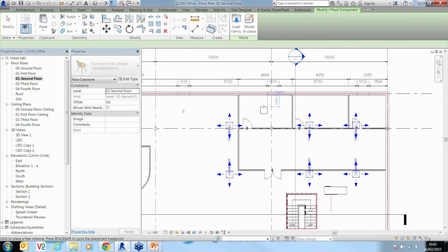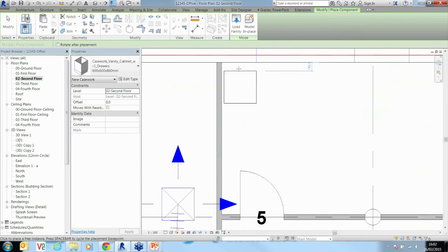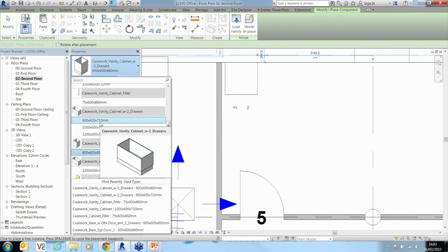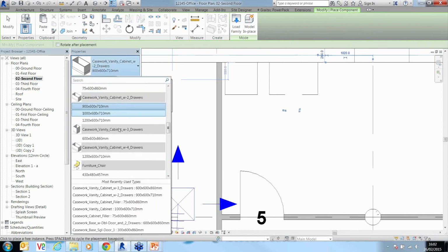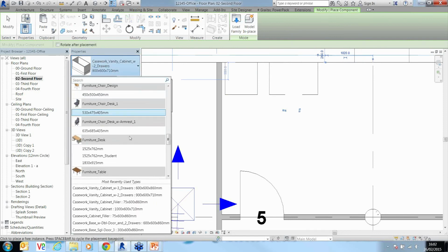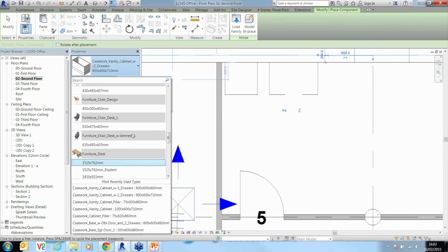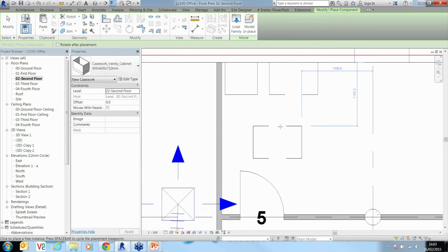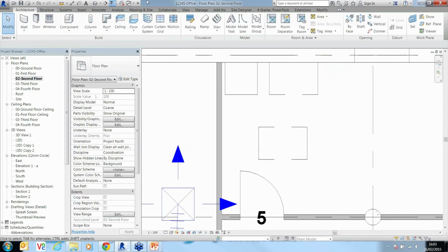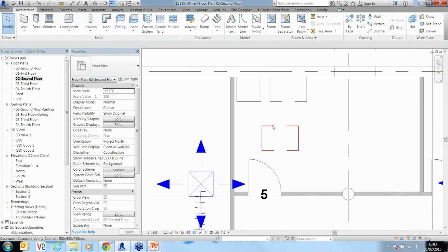But once it's loaded in, yes, I can start placing in kitchen encasements, so I can actually do kitchen modeling if I needed to. So if I go into here, I've got my bits and bobs, so again I can place my kitchen elements in here. So you'll see it's got my different blocks. I can simply place them into my model. Whichever types I've placed in, I know I didn't really select anything more suitable, but you can see here we can place them inside here, and then you've got your kitchen elements in there, which you can start populating, just the same way as furniture.